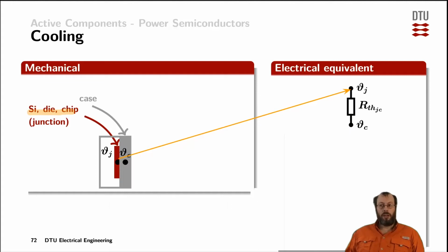Now, in the case of our TO220 packages, you have a big mechanical metal basis on the backside of the die, where the die is mounted for a good thermal conduction. And all the stuff being filled with white here, so you actually can look through it, seen from the top perspective, looking from the top at a TO220 device, is mold or plastic, which contains the silicon and keeps it mechanically in place.